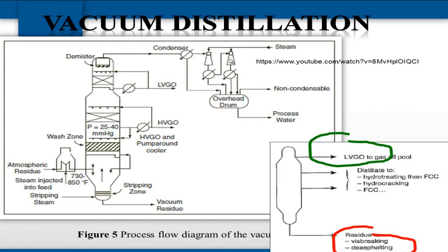The ejector will compress the gas through a nozzle where vapor from the column is sucked into the venturi section. So it means there is a stream coming in with very high velocity, and it will suck the vapor or liquid after condensation to this area and then condense to the products.